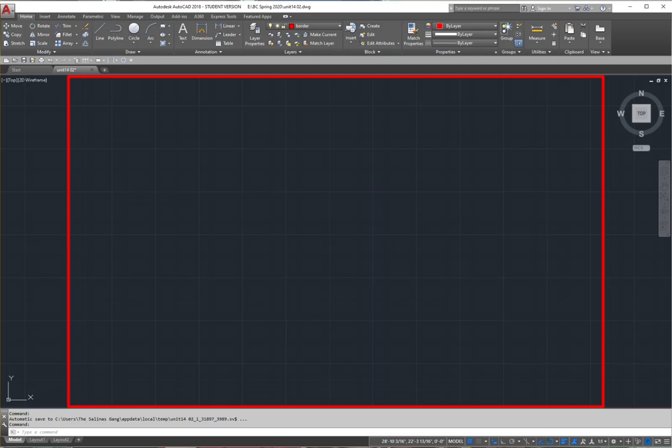On the previous video we reviewed everything that we have done and everything that you would need to begin your new project. We set up our units, our limits, created some layers, text styles, saved as, made a copy, and talked about the different items under your status bar: your grid, your snap mode, your dynamic input, and all those things that you will need to have in place so that you can be as efficient as you can be when you work. So now we're actually going to work on